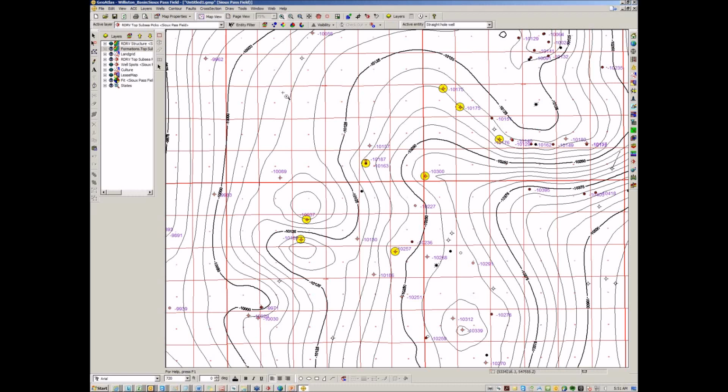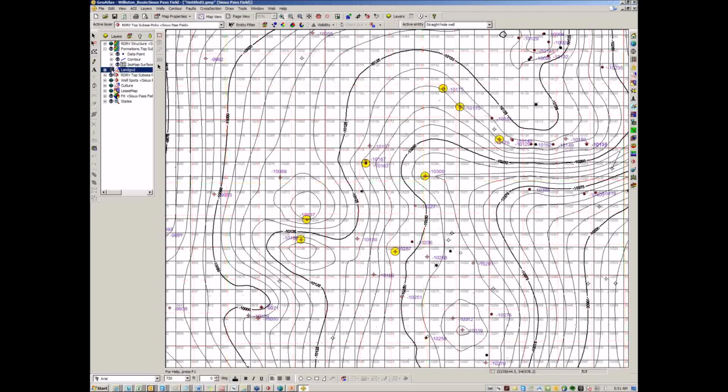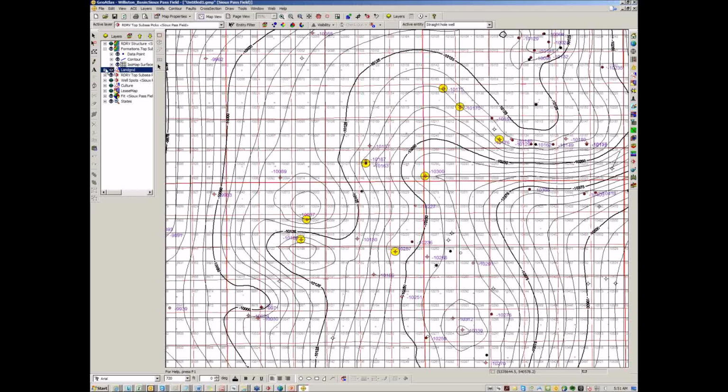honor every individual pick. So first, let's turn on the ISOMAP grid. I mentioned that graph paper. I'll go ahead and turn the eye on, and you can see I just got a gray grid. Now, if I turn off my land grid for a second, this is the grid that the contours are actually lacing through, and it's laid down across the whole AOI. Now, to give you an idea of spacing, I'll turn my land grid back on.